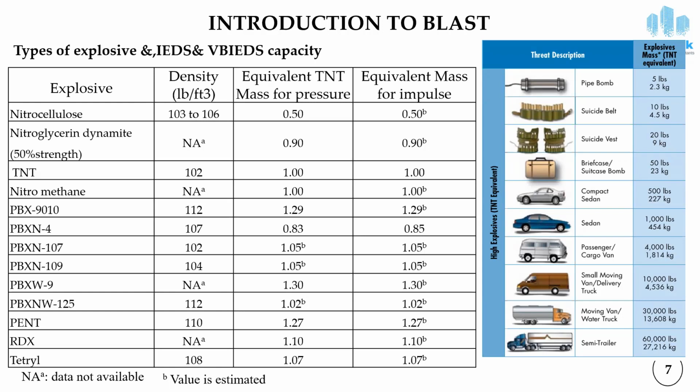I am coming towards your point. If you are designing a building, then you have to decide whether you are allowing trucks to come to that building or not. If you are allowing trucks to enter the perimeter, then you have to keep maximum stand-off distance.